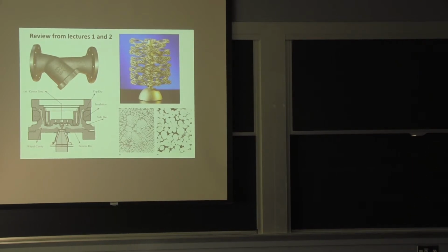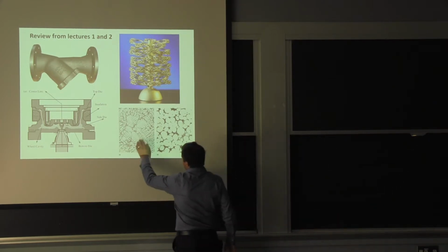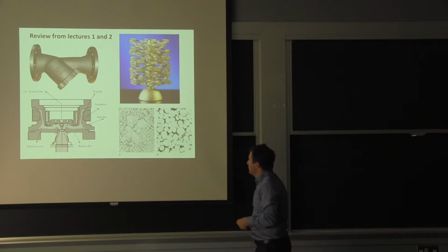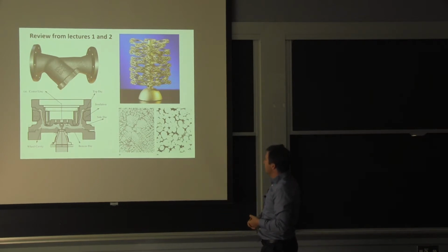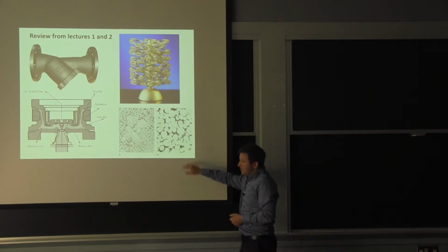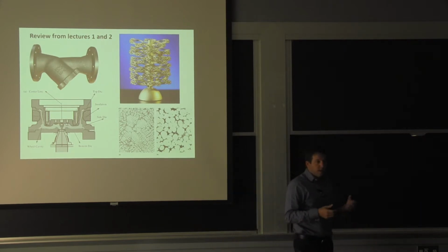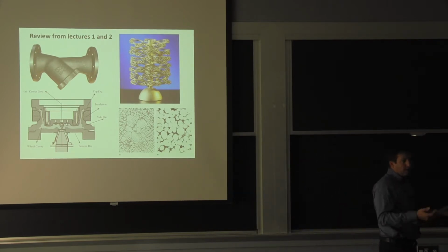At the very end, we discussed that instead of having this dendritic structure and having a casting that has a lot of orientation, you can cast essentially a semi-solid fluid that already had solid in it, a little bit like when you have concrete. You get the aggregate, and then you got the cement. So you're sort of predetermining the microstructure by having already solids in there, and these will grow a little bit, and the space in between is where you have your local solidification.